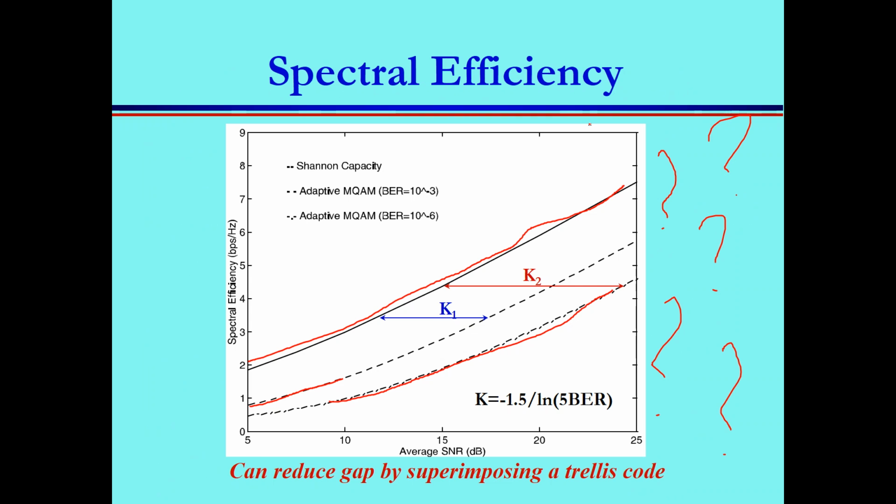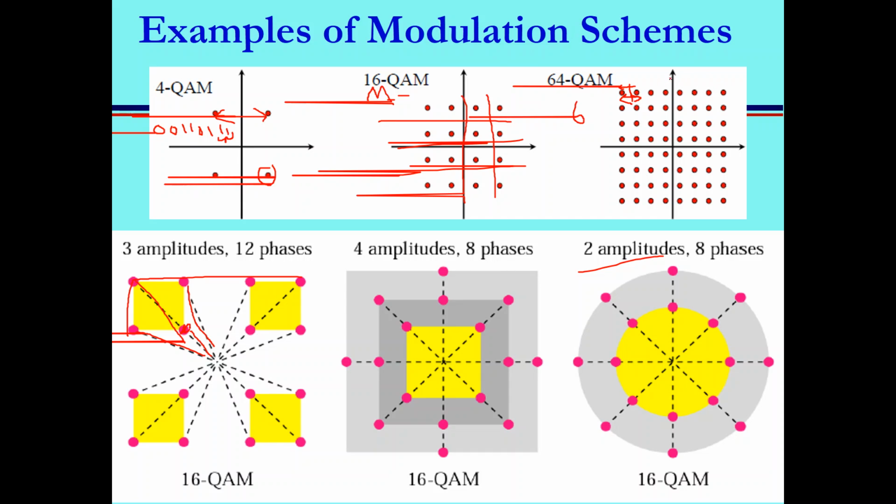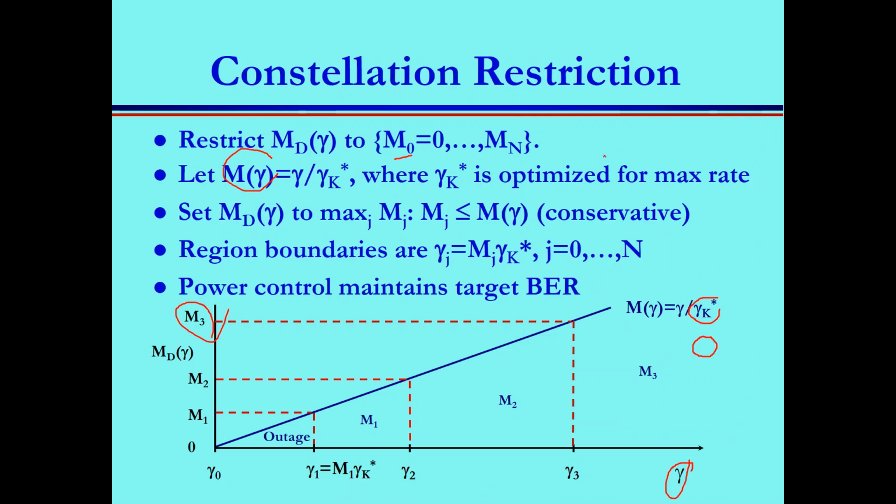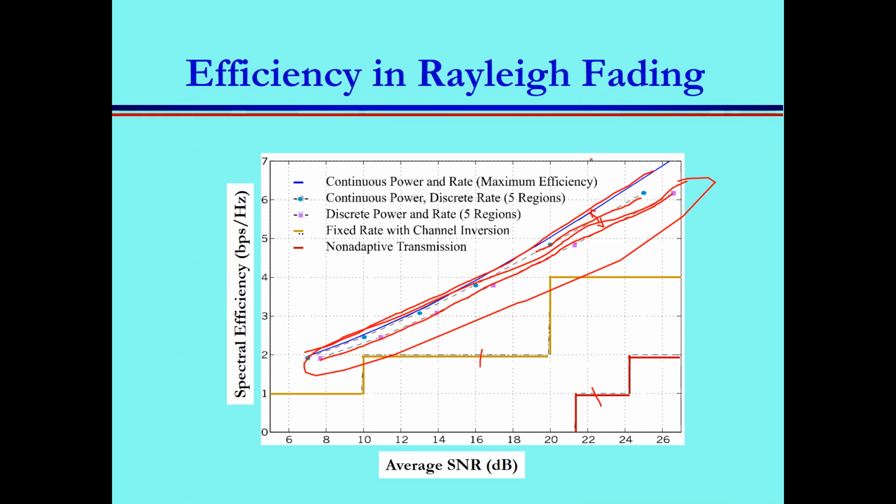The constellation diagram is this. I already explained it before I started talking about the math. This is the constellation diagram: how the symbols are placed in the I and the Q. I, the in-phase, represents the cosine sinusoidal carrier, and the Q represents the sine carrier. By changing their properties in terms of amplitude and phase, this is a representation of how their amplitudes and phases are changing, and these are mapped to data. Clear? This is the constellation. All our talk about M is the number of these points inside the constellation diagram. Because at the end of the day, the x-axis is cosine, the y-axis is sine, and the features of cosine and sine are the amplitude, the phase, and the frequency. QAM uses only amplitude and phase, and changes them based on the incoming information.